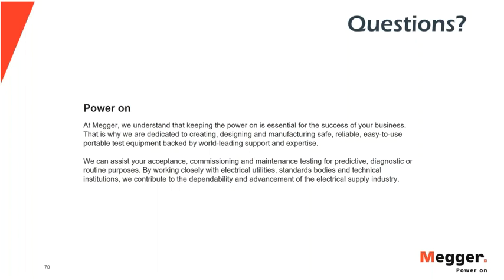It has to be complemented by the temperature value as well, right? It's not the same 0.5% at 20 degrees C trying to compare with a 0.5% at 10 degrees C. Jill, during the presentation, emphasized the importance and the effect of temperature on the dielectric analysis and all this dielectric testing. So you got to be careful on the 0.5%.